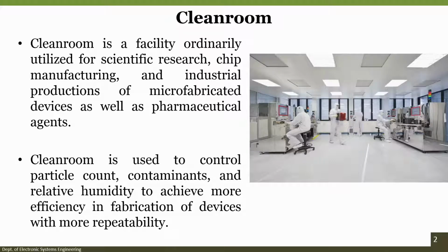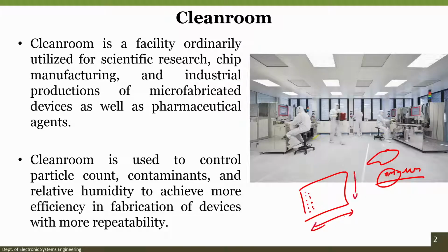So, what is the requirement of a clean room? Let us say you fabricate a chip on a silicon wafer, and there is dust. On this chip there will be millions of transistors, and the size can be anywhere from a few nanometers to a few micrometers. When I say nanometers, it does not mean the actual size of the transistor, it means the channel length. But the overall device would be extremely tiny, and that is why you have millions of transistors on a small 1 millimeter by 1 millimeter chip.